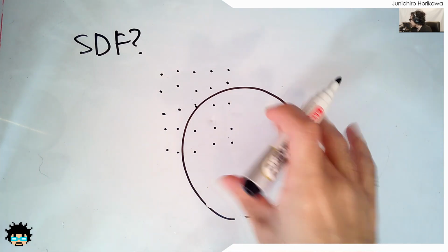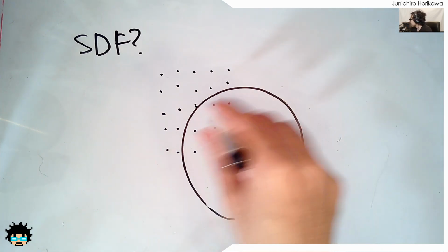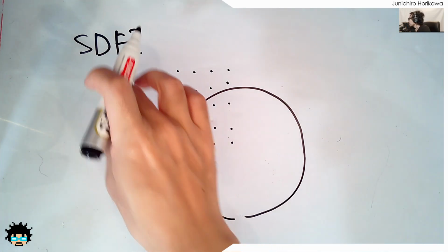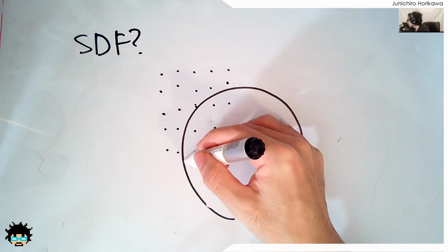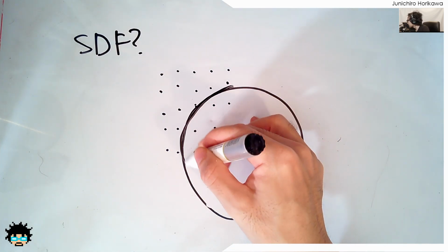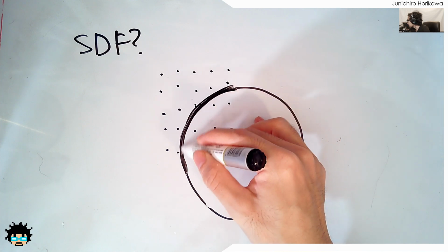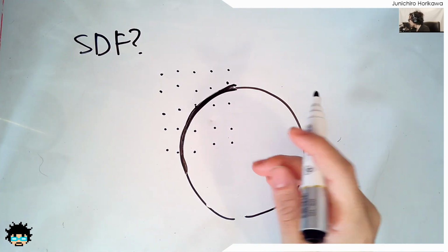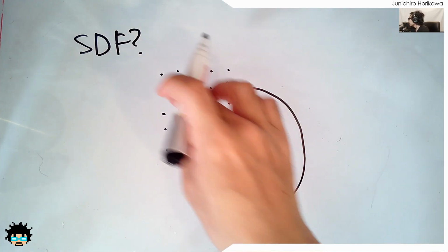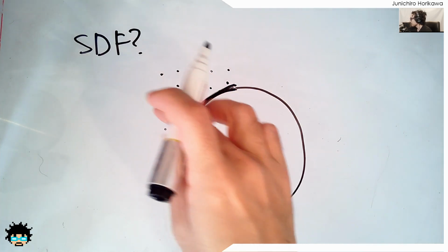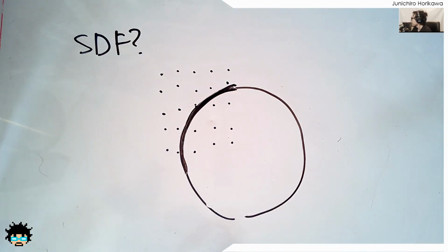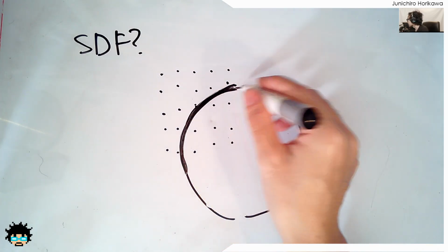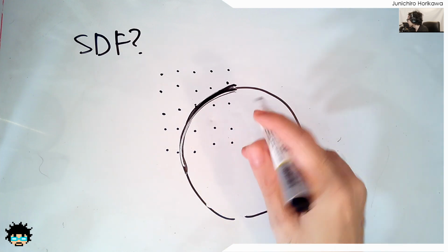Let's say this is the geometry surface that you want to visualize. By using SDF, you can specifically visualize the surface of the geometry by just using the volume values. So the difference is that the SDF volume does not visualize each voxel by its density value, but instead it uses the threshold values of the voxels to visualize it as a surface.